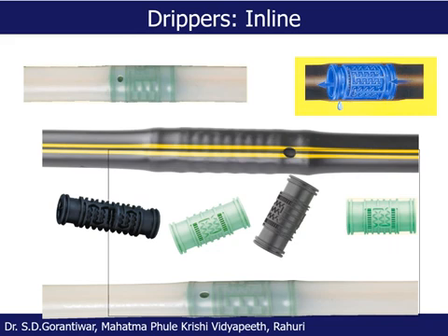For an orchard plantation where the laterals and drippers are located sparsely, if we just take a round in the orchard, we can see the individual drippers as well. If we find that some emitter is not giving proper discharge, or if it is clogged or blocked, then we have to remove it, clean it, or replace it. We can do this very easily for online emitters, but for inline emitters it is very difficult to locate the clogged emitter unless the area near that emitter is dry or the plants are wilted.